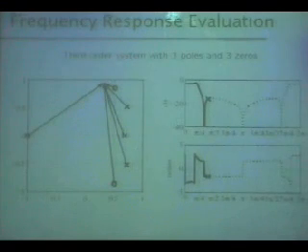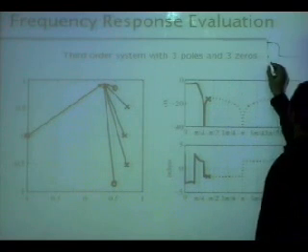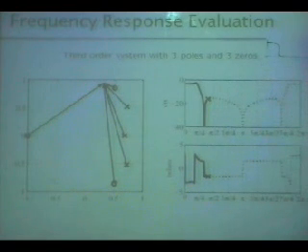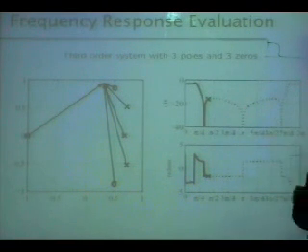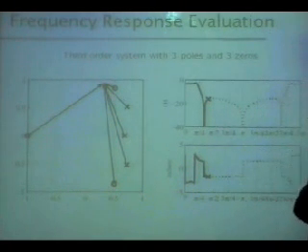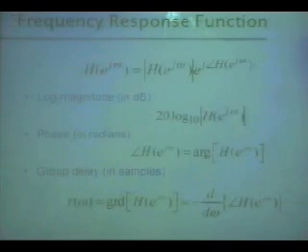Otherwise, if you look at an absolute magnitude plot, it will not show you these details. It will simply show you almost 0. A simple magnitude plot will not reveal a lot of these details. That's why the dB plot is usually preferred, because it gives you more insight into the stop band, and you really want to see how the stop band is.